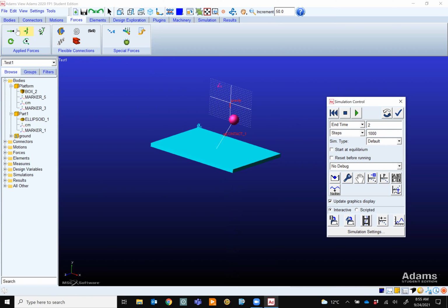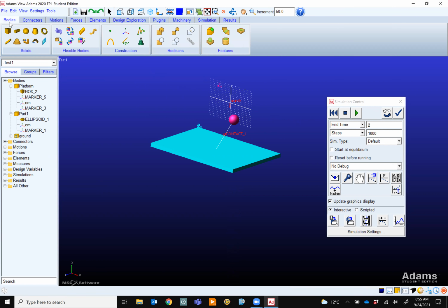And a few quick things here. Each of these, right? So far, we just created this box. You realize that the center of mass, you can choose whether or not to change it. Marker one, again, you can rename all of these, because remember later when you have lots of parts, you forget which one was marker one, which one was marker 5, and then it gets messy.